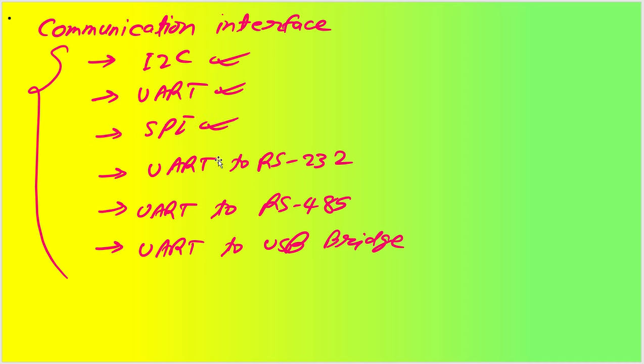These are all utilized in various applications. Let's say I2C is used with photo sensors, or maybe photodiodes, or temperature sensors or pressure sensors. We have UART to USB connection or something like that. We have SPI, generally utilized in, let us say, ADC communication. I2C is also used in your IO expanders. So in that case you can utilize them.